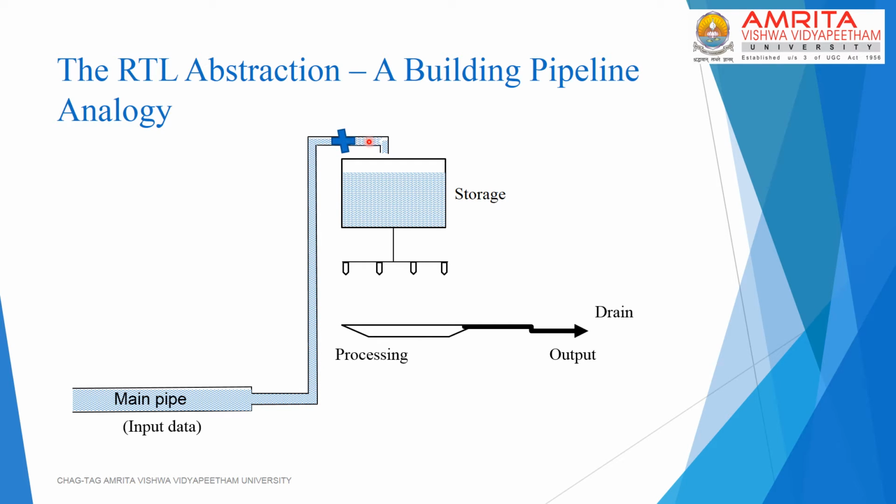Likewise, in a digital system, the data that flows into the system is manipulated by the data path elements, of course under control from the control path, and it changes its form. The manipulation may be in the form of arithmetic operations like addition or subtraction or shifting. Eventually, the data is output from the system, either through the output buses or through the registers again.